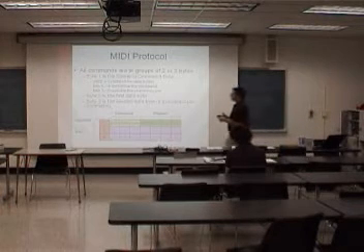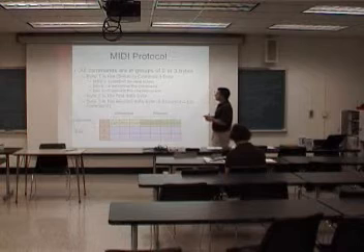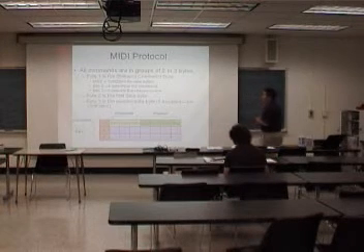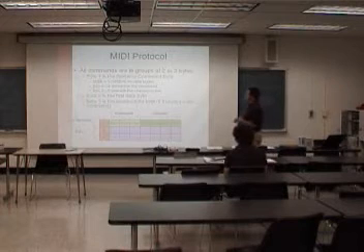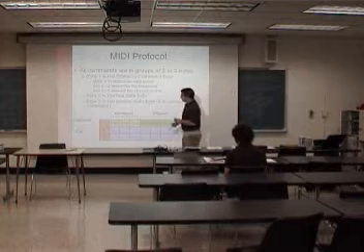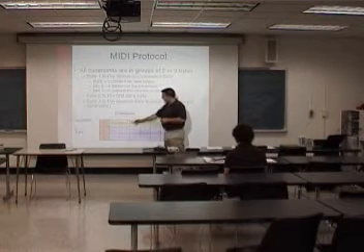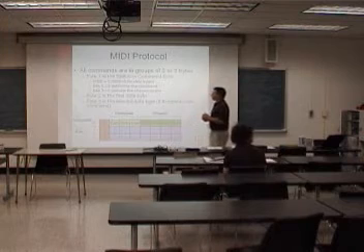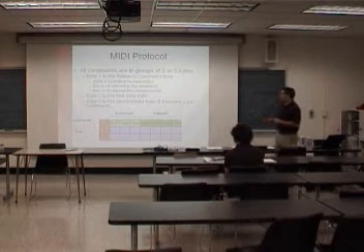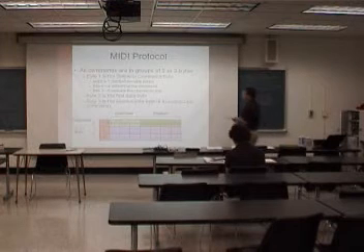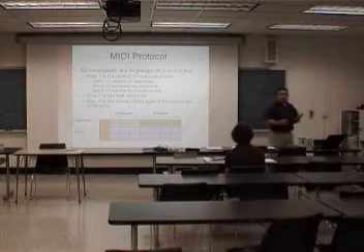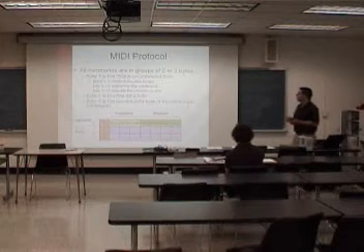Although they're all fixed length or have delimiters, so it's not completely clear why that's necessary, but it does make it easy. Okay, so the MSB is 1. The next 3 bits determine which command it is. So there are 7 commands roughly. The 4 least significant bits determine the channel. So again, I said you can have 16 channels, so 4 bits.